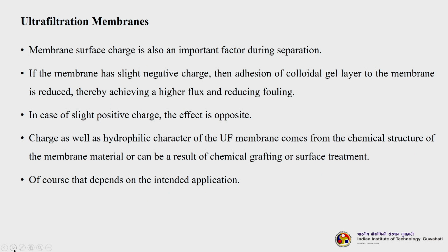Membrane surface charge also plays a very important role during the separation. If the membrane has a slight negative charge, then adhesion of the colloidal gel layer to the membrane is reduced, thereby achieving a higher flux and reducing subsequent fouling. But in case of a slight positive charge, the effect is reverse.